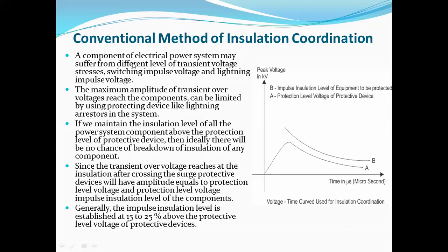Generally the impulse insulation level is established at 15 to 25% above the protective level voltage of insulation, right?